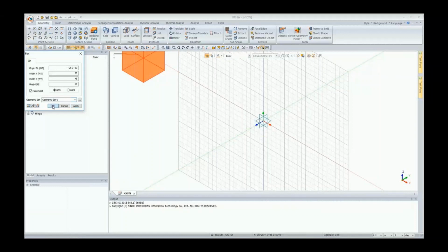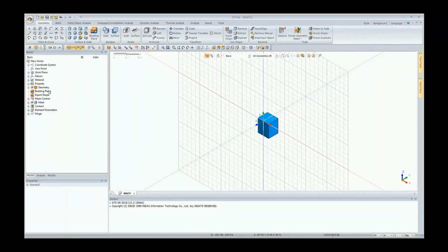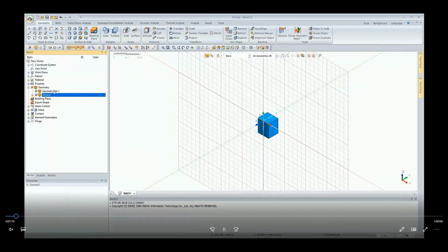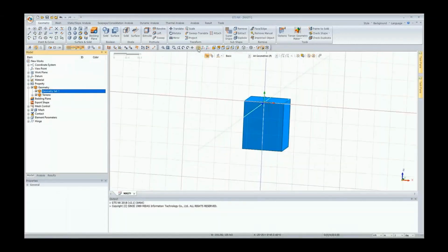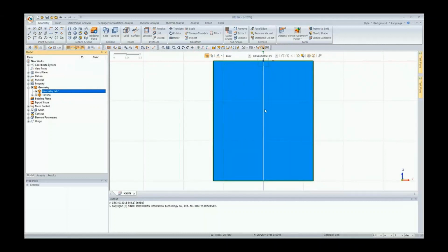And I say okay. We'll see now this has generated the first geometry, and if we wanted to explore it, it would be under the set terrain. I now go to the front view, and what I'm going to do here is draw the faces of the tunnel, as well as the primary and secondary supports. So I'll end up drawing three circles.